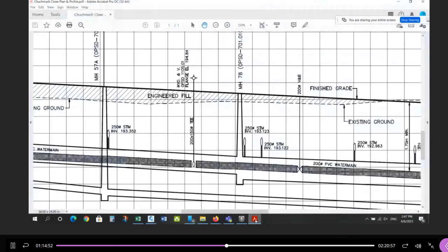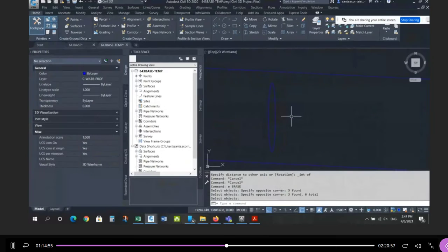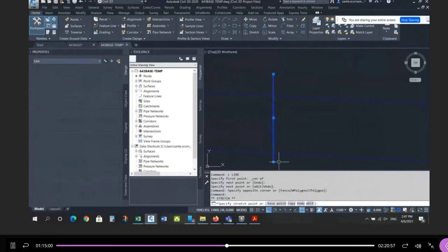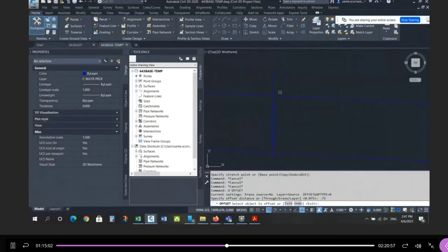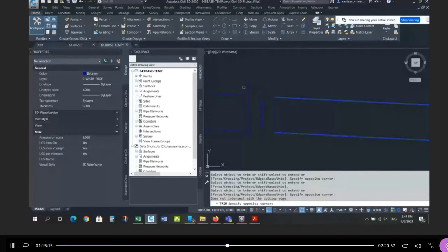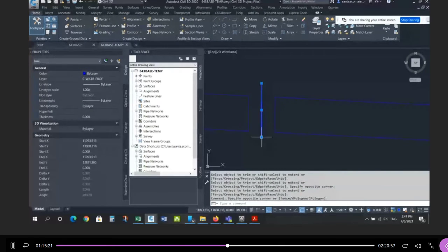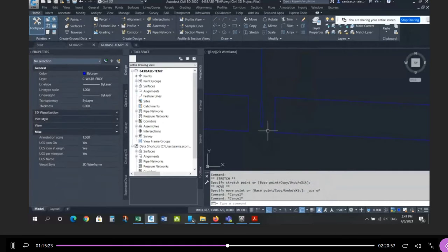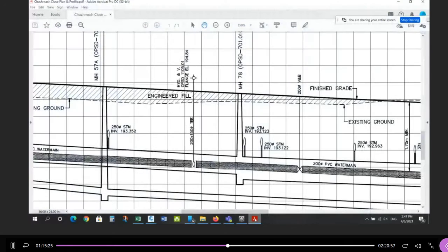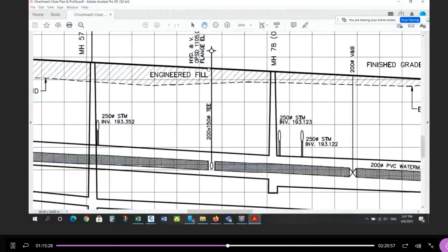Okay, we'll go back to here, and it's broken. So I'm going to use the same offset. I'm going to draw a line from the center, and I'm going to offset at 0.75, the same gap I'm using on the valve box, right? It's the same gap I'm using here, just to be consistent, and then it breaks the pipe. And we keep this. And then this starts at the top, quad, and that looks a lot like what's happening here. And then it goes up and beyond.